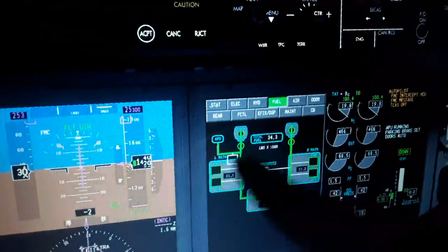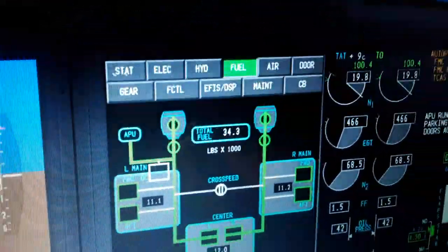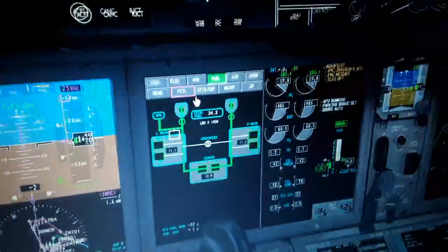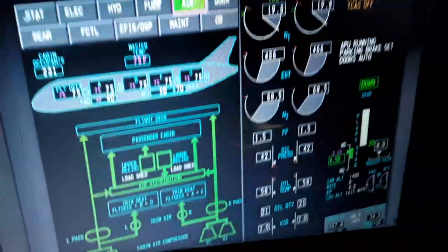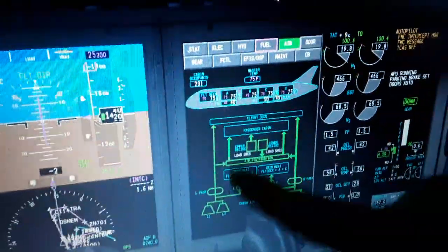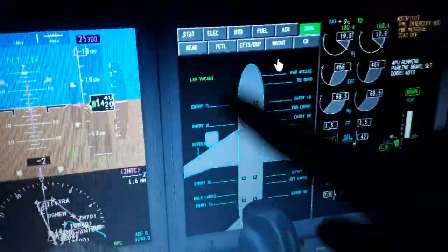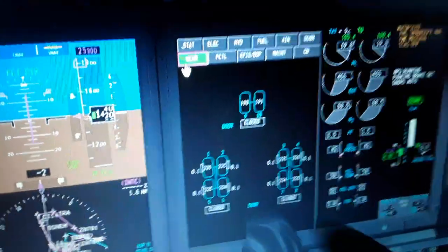We have the recirculation of the fuel all the time from the tanks into the engines using the fuel recirculation system to remove the heat from the engines and cool them down, and also heat up the fuel so it won't freeze in flight. Also for the oil that is being recirculated from the engine parts. So we have here automatically the air system, pressure inside the cockpit and the pressurization from the engines. The doors are closed, the cabin can be pressurized, the gear, the temperature of the brakes here, and the pressure of the tires, flight controls.